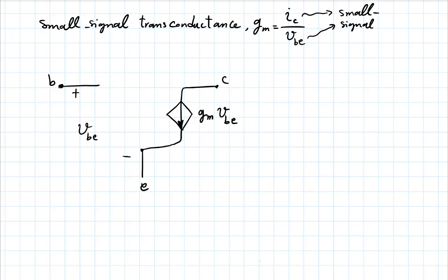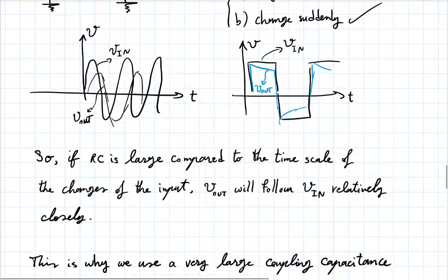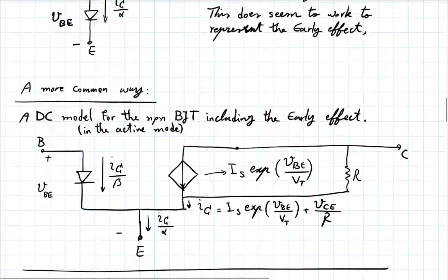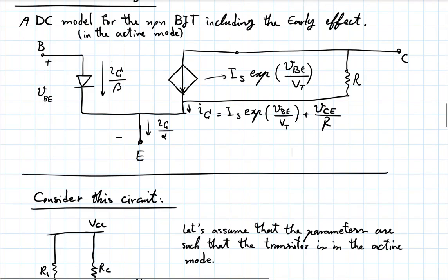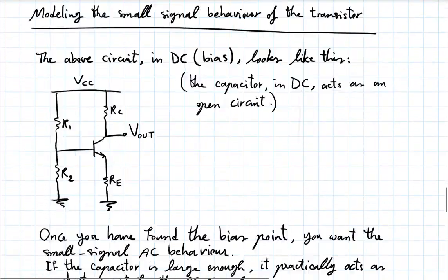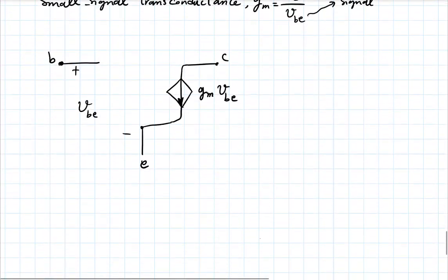So this is very similar to the large signal model. We had the collector current depending on the base-emitter voltage, but that was the full description, the full exponential dependence. In small signal, that exponential dependence has been replaced by a linear dependence, just a proportionality, gm times v_be rather than an exponential of v_BE, because you're looking at a small section of the curve.